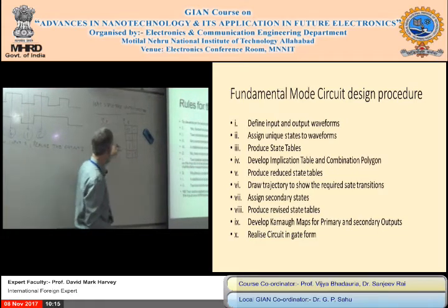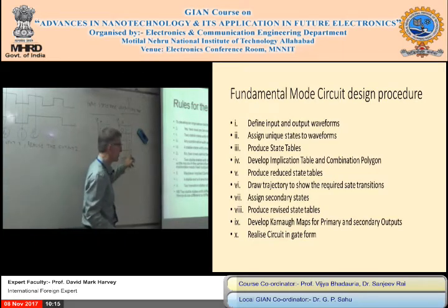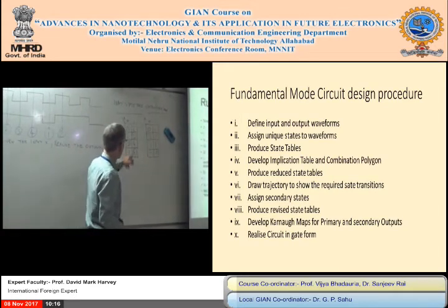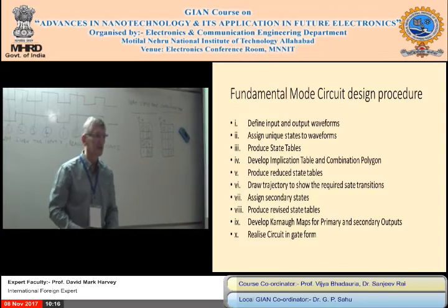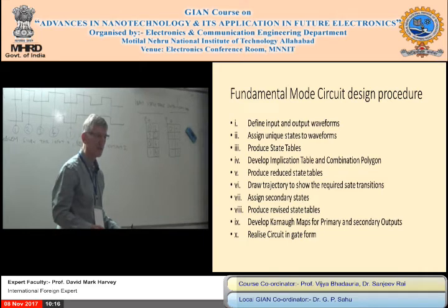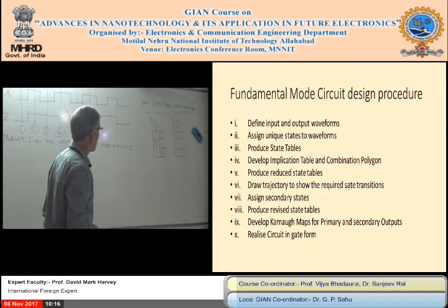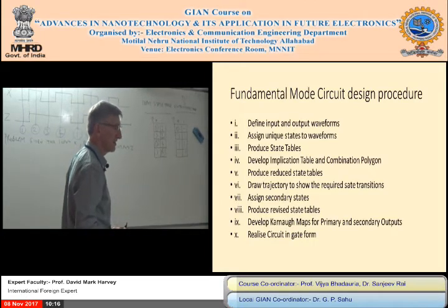If you look at the other 2 stable states, 2 and 4, in the input x equals 1 column, both their outputs are the same. So on that column, you could combine them. But when we look at 2 and 4, you have to look at 1 and 3 as well. And 1 and 3 we'll find out can't be combined. So nothing can be combined, but you don't know that yet. So this is impossible because you physically can't realize that as your circuit. So that's for no. And these are the implied ones, which is why we draw this implication table. And maybe you can't make a decision on it.